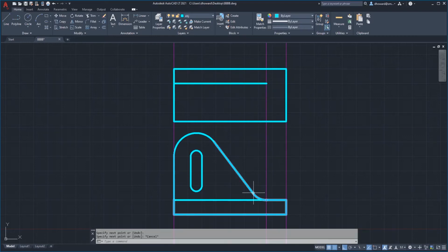So that's where that tangent arc ends, that round ends right there. So that's where that line will end. Okay, the top view is going to have some holes in here. It's also going to have some rounds. Let's do the rounds. Now that you guys know how to do them, know how to cheat them, let's cheat them. We're going to go to these, technically they're called fillets. We're going to go to the fillets and we'll just make these immediately.